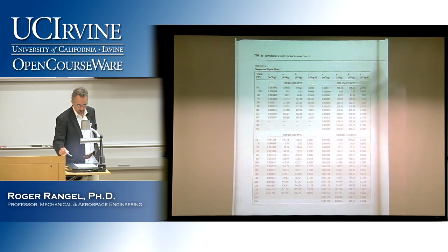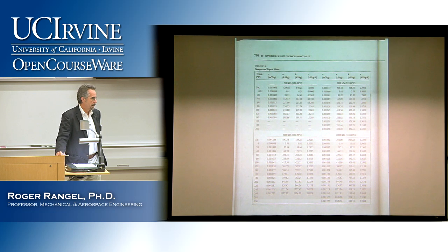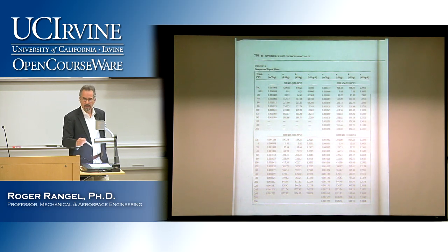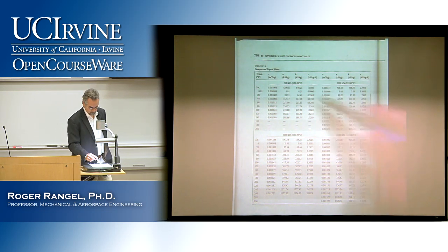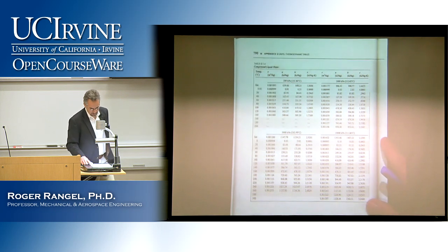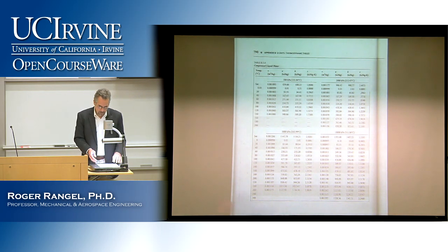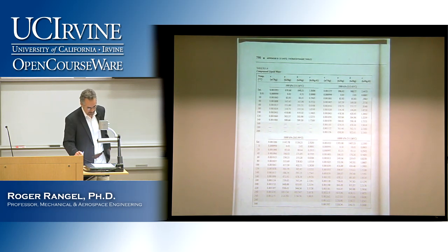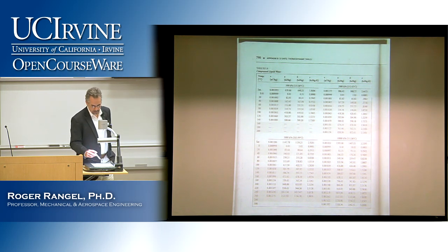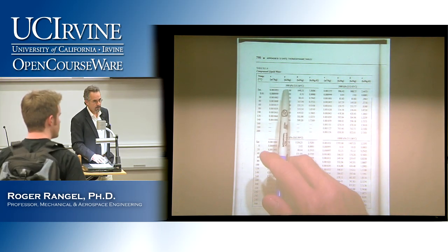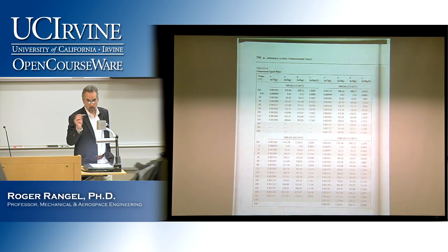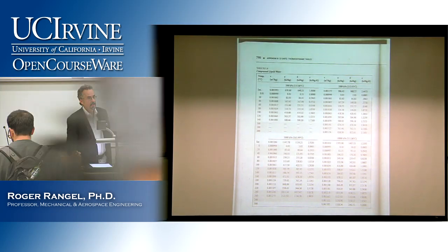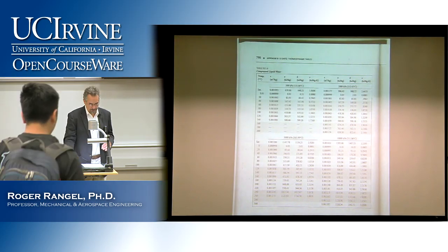So if you are somewhere in between, suppose that your pressure is 1,000 or 700 or 1,200, then you would have to do some interpolations, which gets tedious. And sometimes you just don't have the data. For example, if you just have a small amount of compression, maybe it's only 200 kilopascals, you may not even have a table because there is not enough of a compression there. So the way to handle that situation